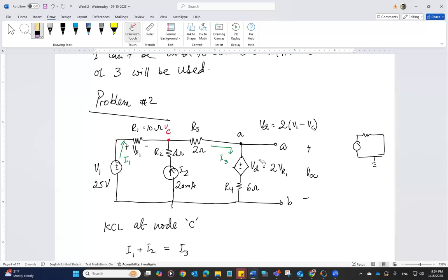Once again, if you do have passive components, and you put a short circuit in parallel to those passive components, no current is going to go through them, then you can safely eliminate those components, remove them from the circuit. In this case, we cannot do that. So we're just going to put a short circuit over here, and the rest of the circuit is just going to stay the same. And then we're going to use one of the circuit techniques to find the short circuit current. So let's go ahead and do that.